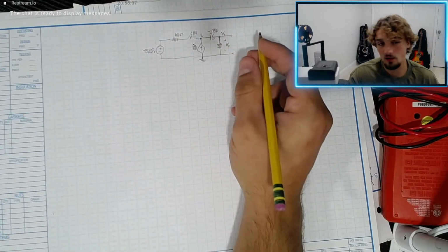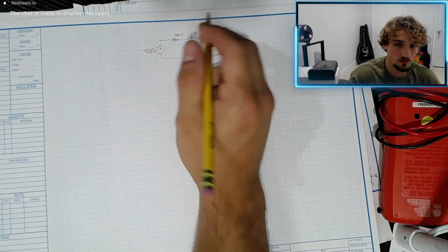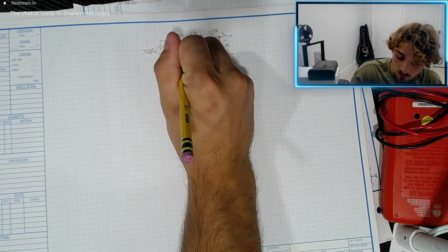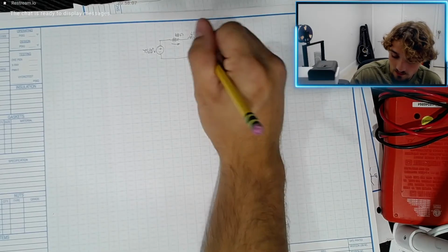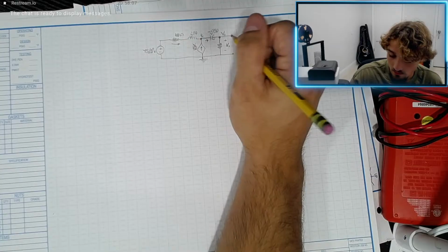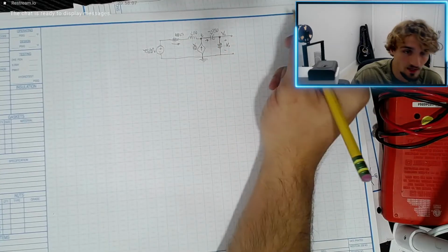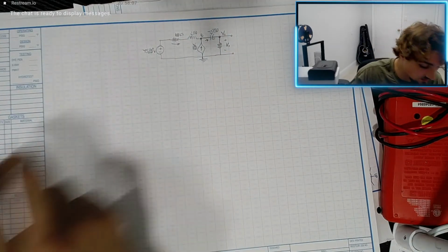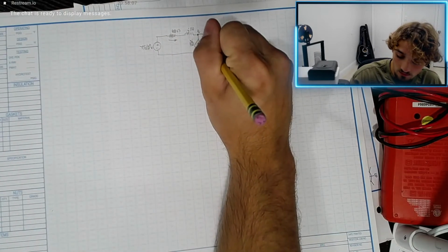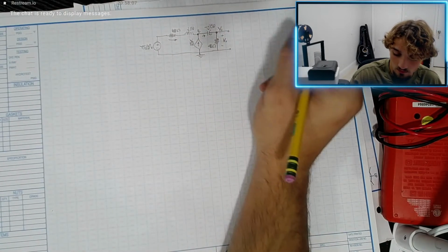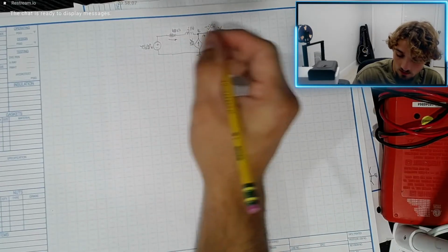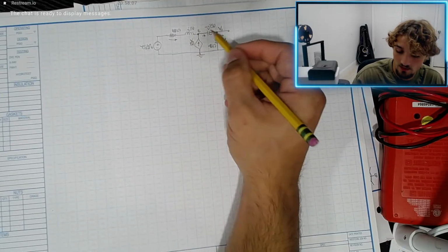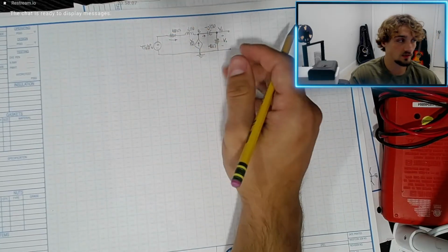So we just set up a node analysis, okay? And then we'd consider this current, that's a current, and this current exiting this node E. Then V out divided by, what is the magnitude of this resistance? 40 ohms. So 75, 600, J 50, that's an imaginary number. It's equivalent to I, same thing. We're just going to use J so as not to get confused with the current.